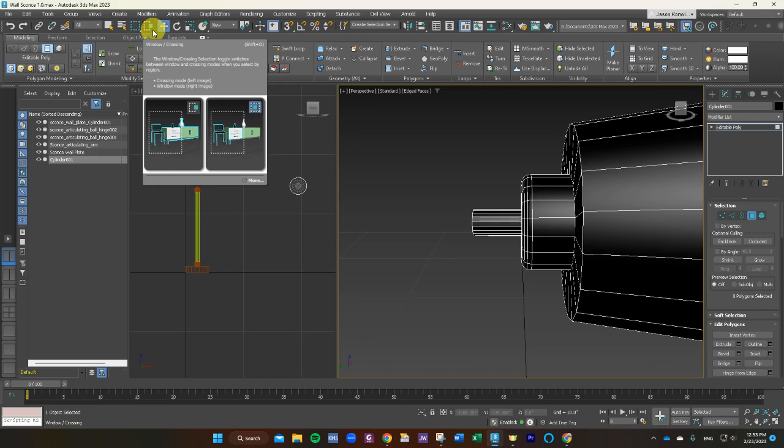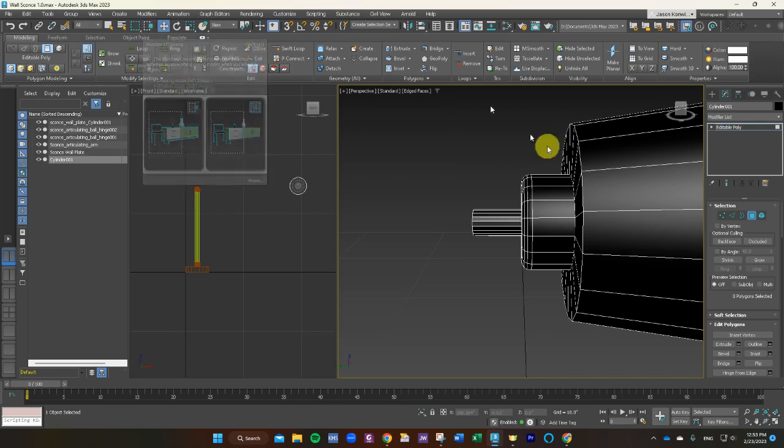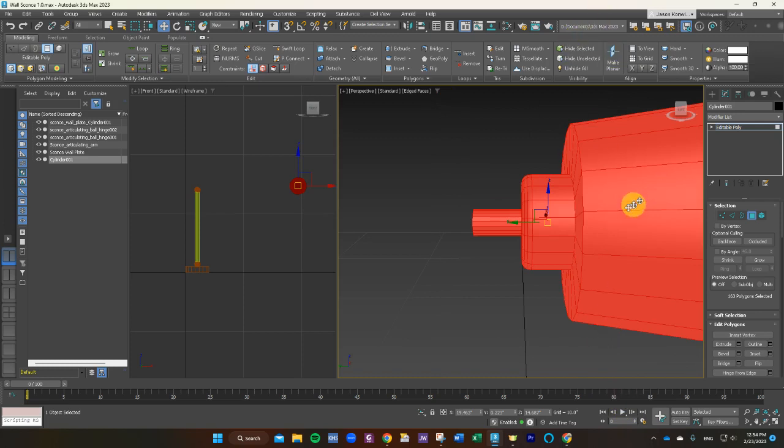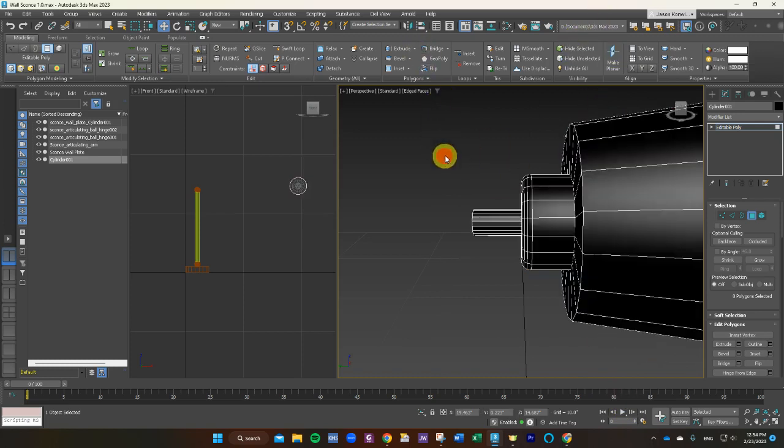That right line on the box that we're drawing around the subject also includes and paints in the rest of the cabinet. Okay, so the window mode only grabs any full shapes that are inside the window. So let's try this. I'm in crossing mode. If I draw a box, I'm just going to start out here and draw a box around here and go like that. It paints everything, okay, because these also crossed in the box.